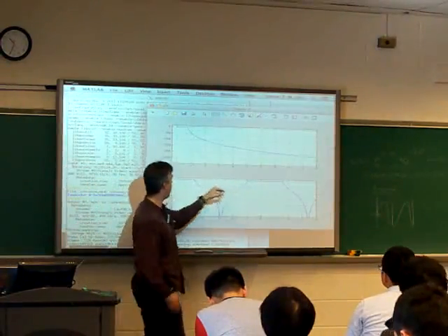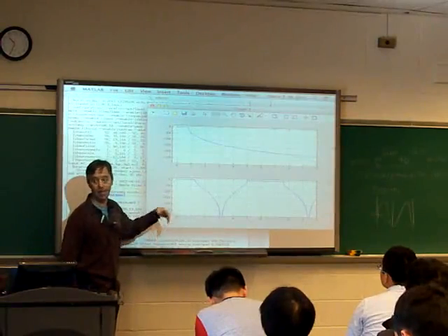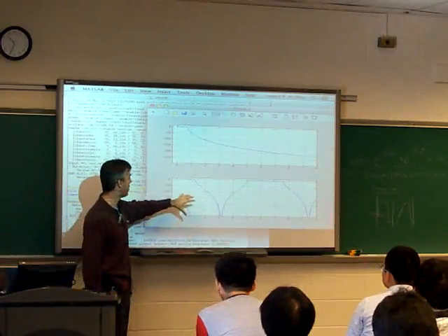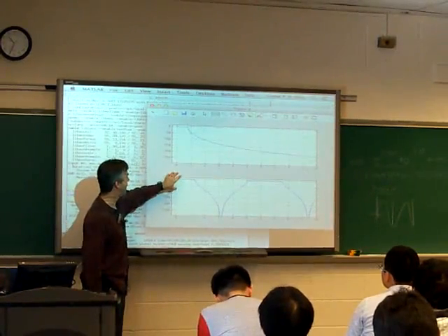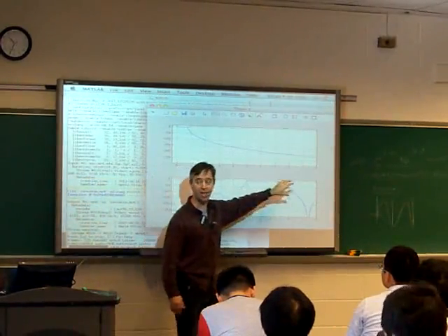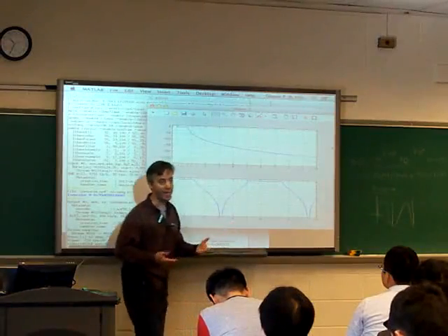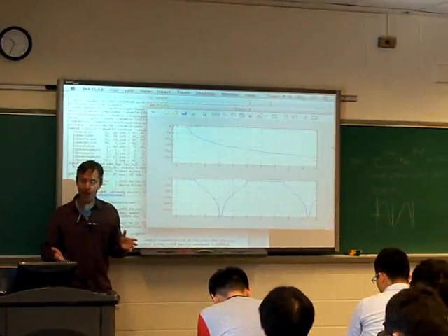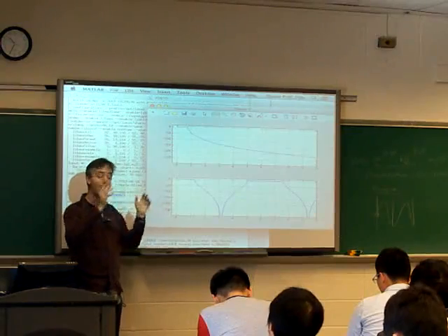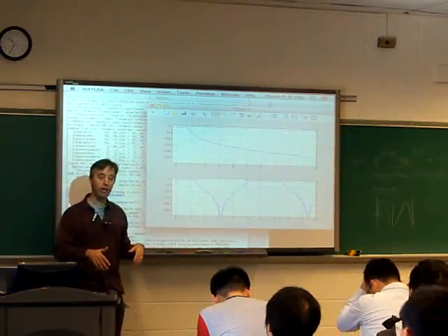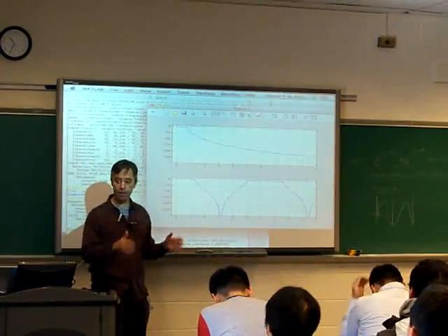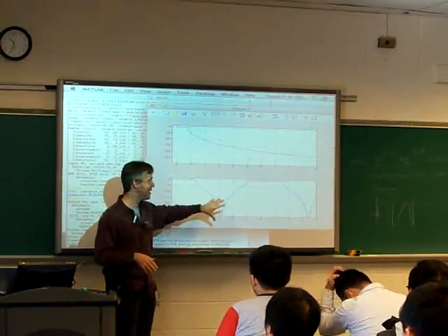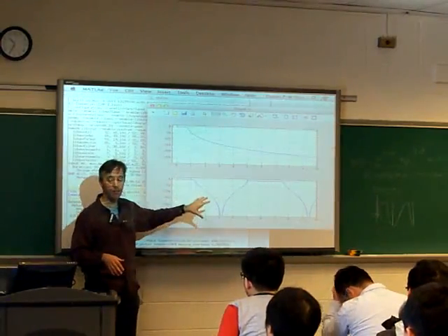It'll alias it down to make it appear like a frequency down here, and then that's now within the passband, and so it'll go through fine. But the problem is not in the design of the discrete time filter, because of course, if we want to have large gains in here, then we're obligated by the periodicity to have them every other place. The problem is in how we sample the original signal. Before we even put this into the discrete time domain, we've got to take our continuous signal and make sure it is band limited to below half the sampling rate, below the Nyquist rate. Otherwise, we're going to get horrible stuff. But that comes much earlier than the problem of the system itself.